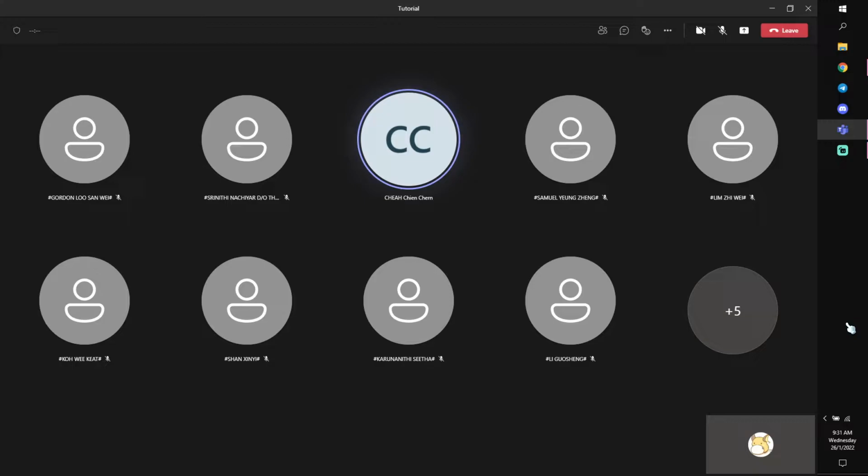Okay, let us review some of the concepts that we have discussed in the last tutorial, namely nodal analysis. Nodal analysis mainly consists of 3 main steps. Firstly, you assign node voltages with respect to a reference node. Now, reference node is referring to, for example, this node which is connected to ground. And then all the node voltages are defined with respect to this reference node.